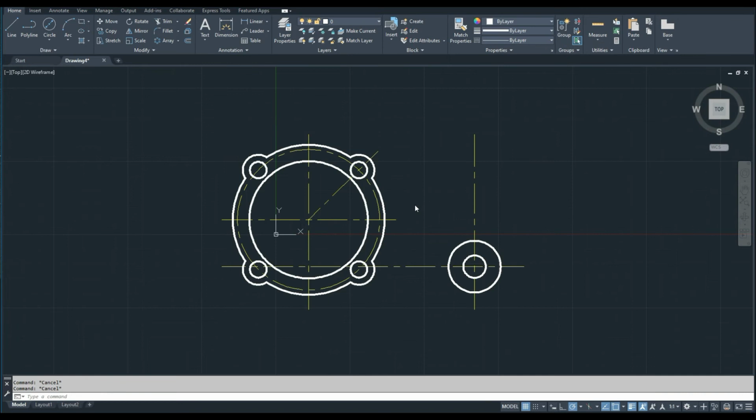How can I draw a line tangent, tangent? Guys, I will be sure that in the snap we have the tangent. Right click and choose tangent. Keep tangent on. Click. Choose the line. Okay, come to here. I can't see the tangent. What should I do, guys? I will use this option. Take care. I will turn off the snap.